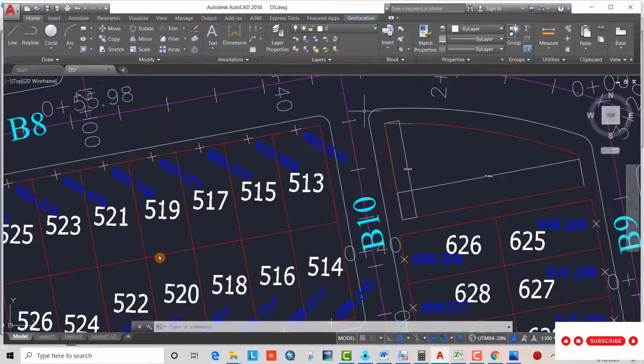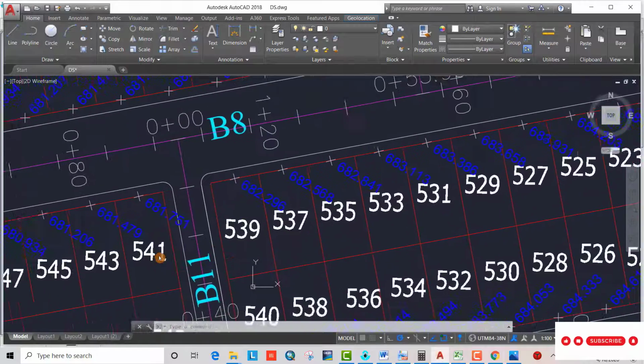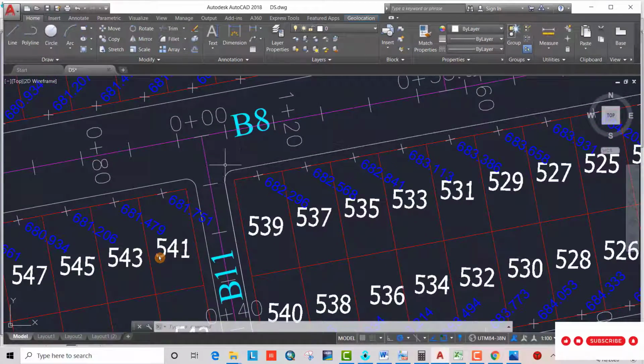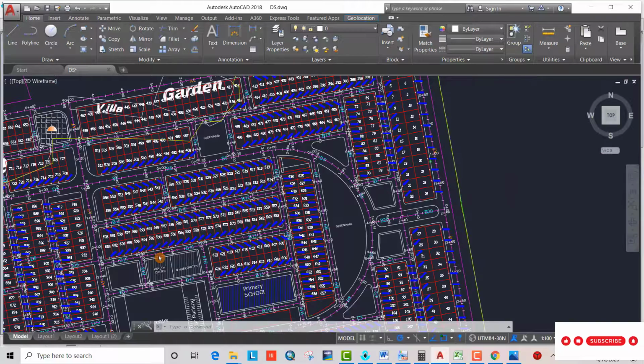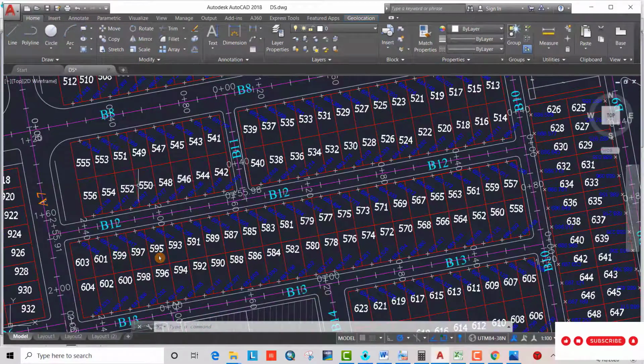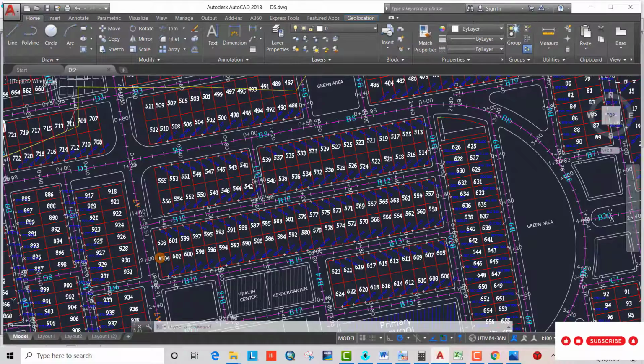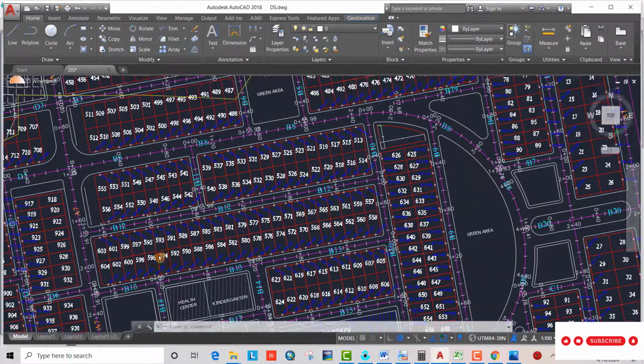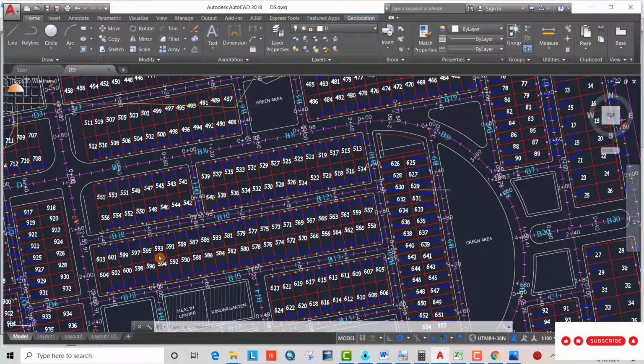I choose here, and you see the elevation is 685.838 meter. And also you can see the elevations, and I provide the note here, which is the elevation is 679.84, and here is, yes, you can just look at the map and bring the elevation. It takes time, so I provide the elevation for the nodes.